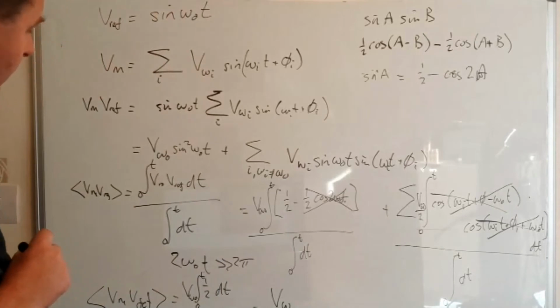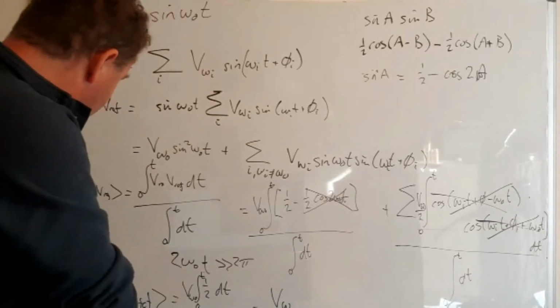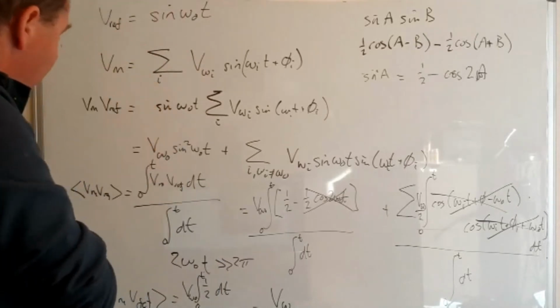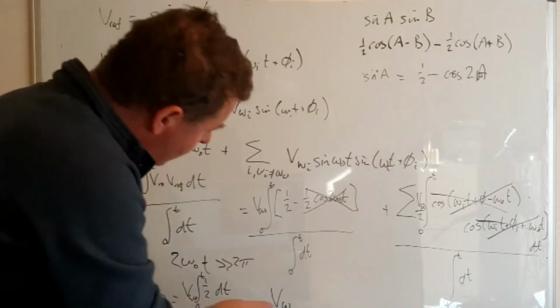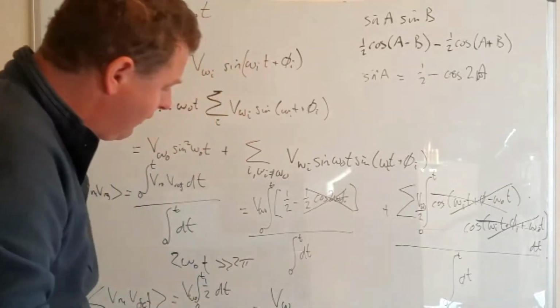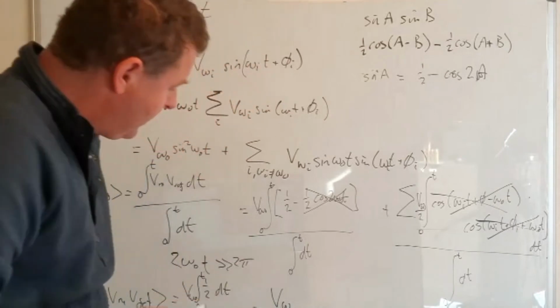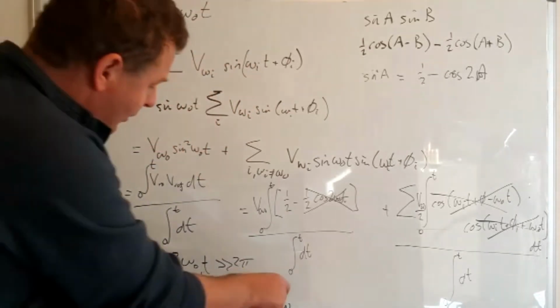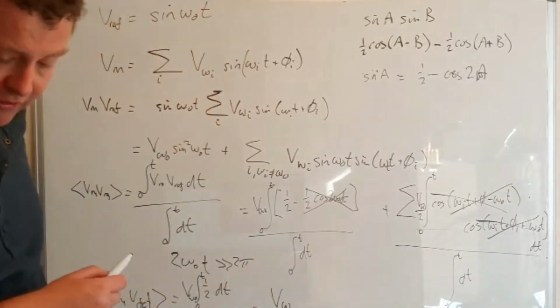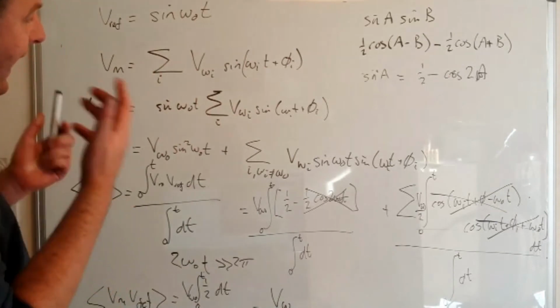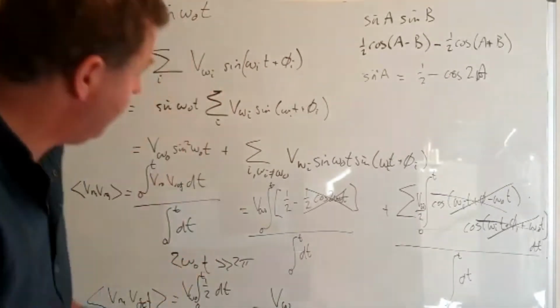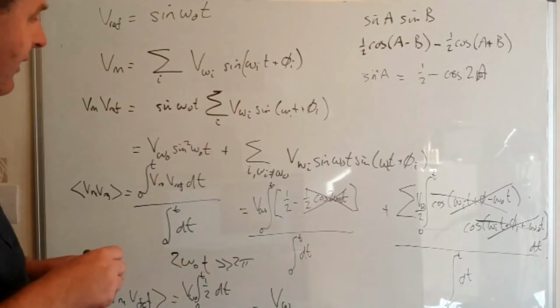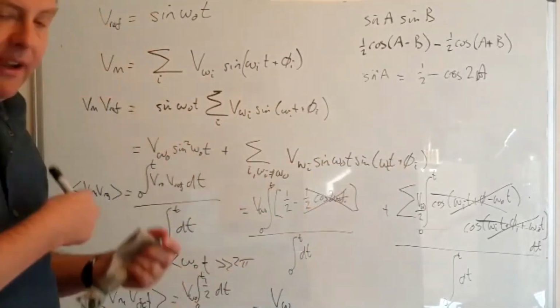And so what we've done is, by multiplying by our reference signal and then averaging for a very long time, we're left with only v omega naught over 2, which is the signal we're actually interested in measuring. And so that's why what we get tells us exactly the signal we're trying to measure, and it doesn't matter what other signals are there, they all just cancel themselves out.